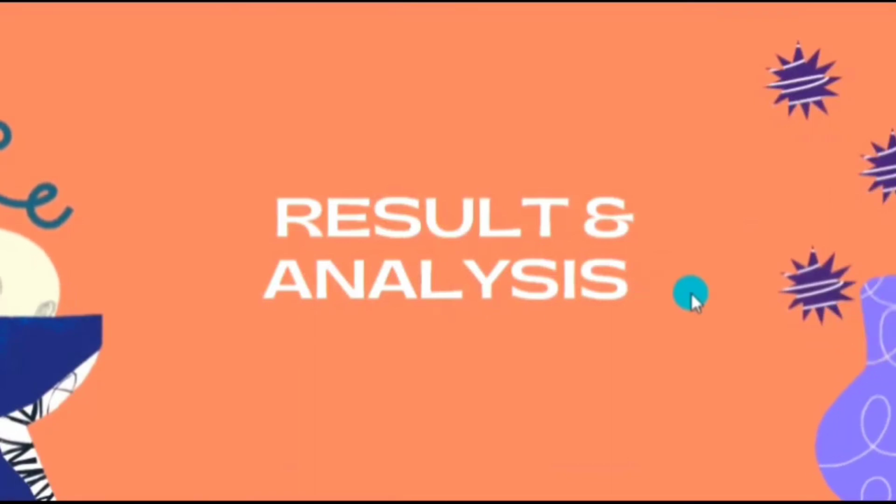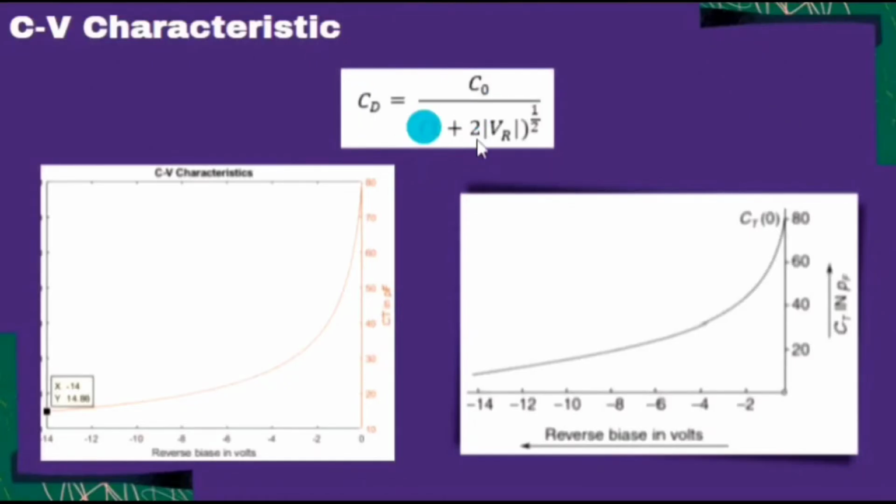Okay, for the result and analysis, this is the related formula to simulate the CV characteristic. The results show the nonlinear capacitance curve is inversely proportional to the reverse bias voltage of the varactor diode, which is varying from 0 volt until 15 volt. It could be compared with the theoretical curve where the operating voltage of 15 volt gives 13 picofarad, which is quite familiar with the value of capacitance from the simulation result.